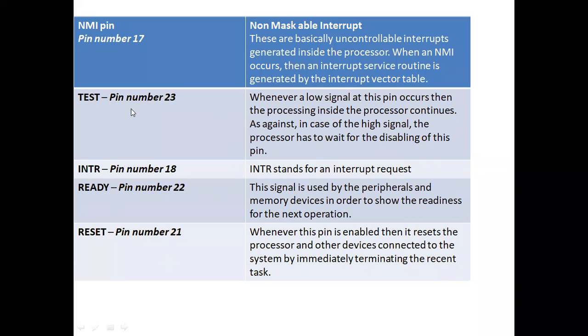So in this lecture again we will learn the pin functions. As discussed previously, NMI is a non-maskable interrupt pin. Whenever we want to create an interrupt, we should not disturb the functionality of the processor. At that time NMI is used. Otherwise INTR is used, which is a maskable interrupt.